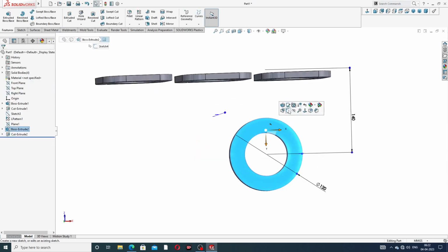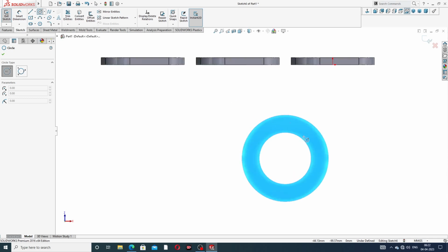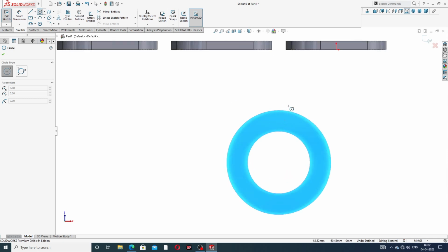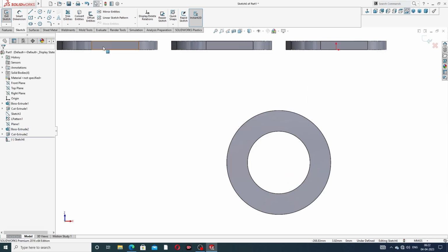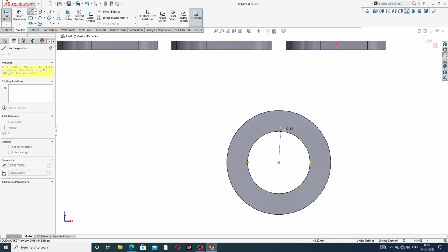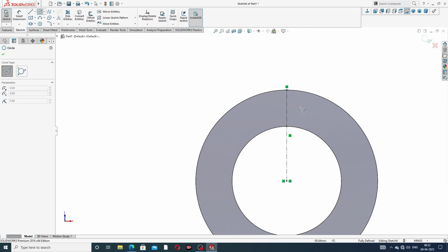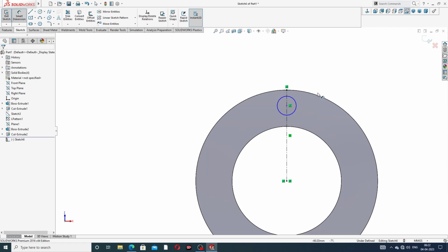And again select a sketch normal, because this is for a pattern, and a circle is drawn here. At first create a line. The line is a center line, drawn from this point to this point. Then click a small circle and align a dimension.